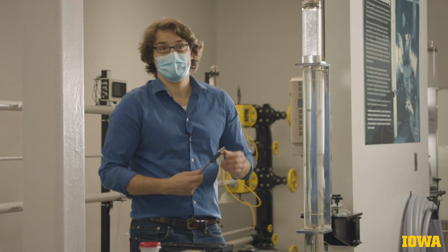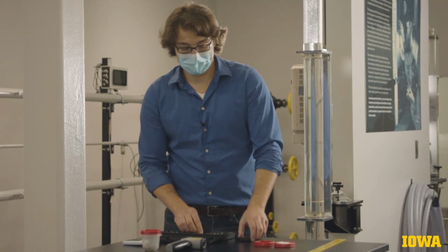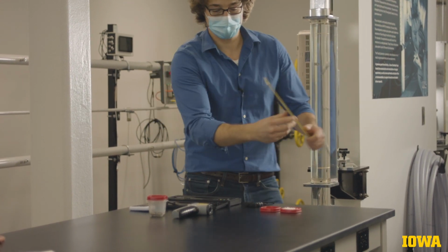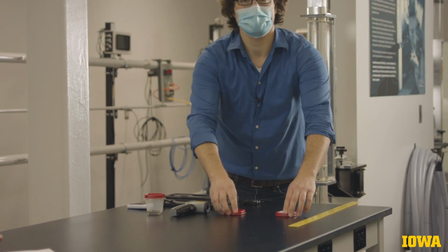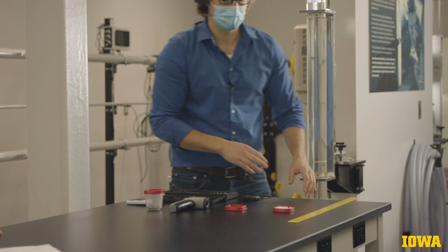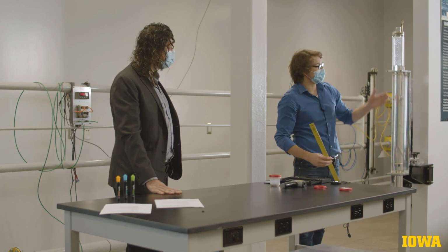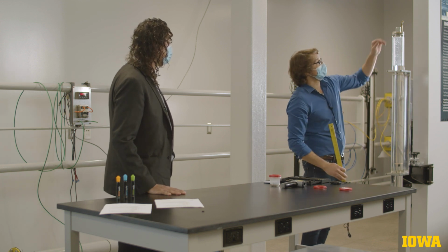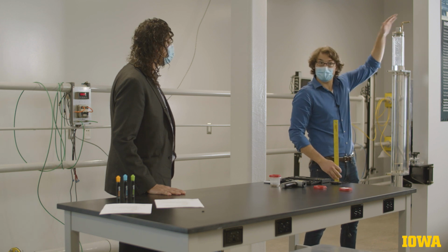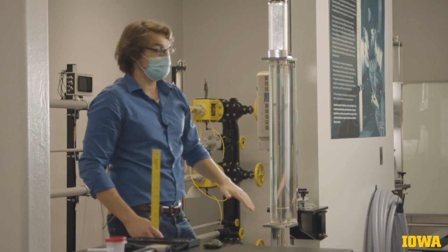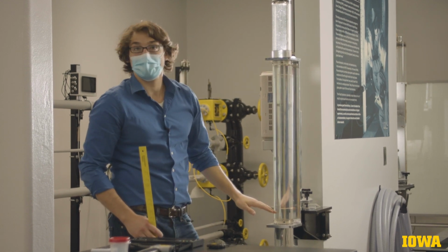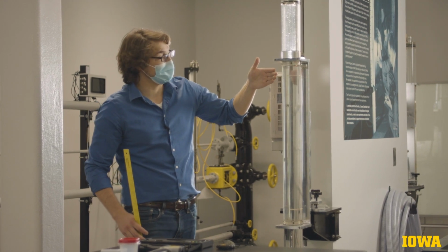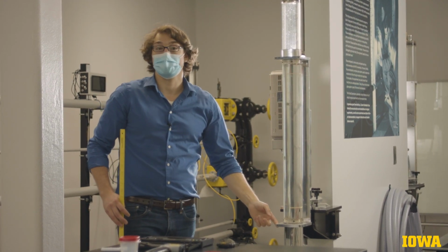They consist of a standard set of calipers, a stopwatch, a linear rule, of course our set of spheres that we'll be testing, and of course the experimental setup behind me, which is a circular tube filled with glycerin that's equipped with a gate at the top that allows us to open it and allow a sphere to begin falling, as well as upper and lower lines scribed into the tube so that we can time how long it takes the sphere to descend a known distance so we can find its terminal velocity.